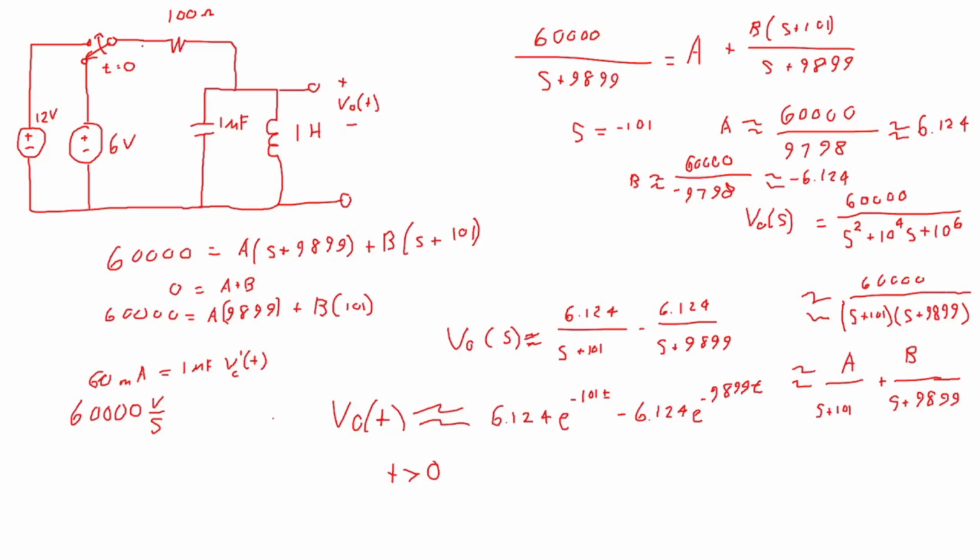And so it's when it's critically damped that both the charging and discharging cycles are very quick. And so you get this very speedy decay when you're critically damped, whereas when you're overdamped, there is a slow decay and a fast moving term. And so the slow one wins out in a lot of cases. When you are underdamped, there's just not enough dissipation.